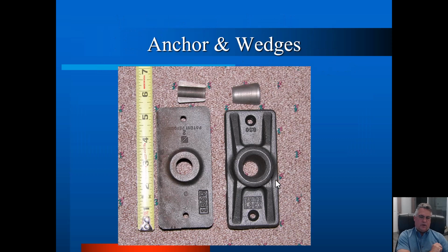So these are the anchors. This is unbonded post-tension concrete. The only way that the force gets into the concrete, since the tendons are not in any contact with the concrete, is at the anchors at the end. Now, it only takes one anchor at the end to anchor a tendon, but I'm showing you both sides. So I've shown two anchors in this.